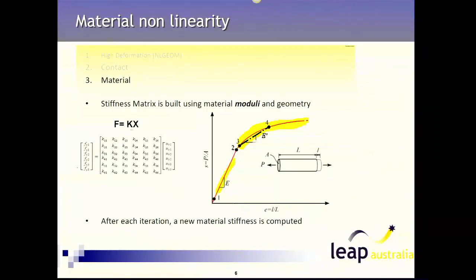Depending on the behaviour in this plastic zone of the material, we can have different ways of describing that material property. It usually comes down to where your material data comes from. As an absolute minimum, you would have just one slope that describes your nonlinear behaviour. Even though that's in effect a linear slope, it's still considered a nonlinear behaviour, because there could be parts of your structure that are still elastic, and other parts that are in the plastic zone.